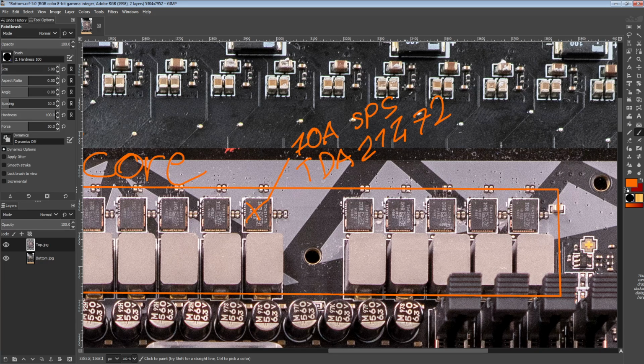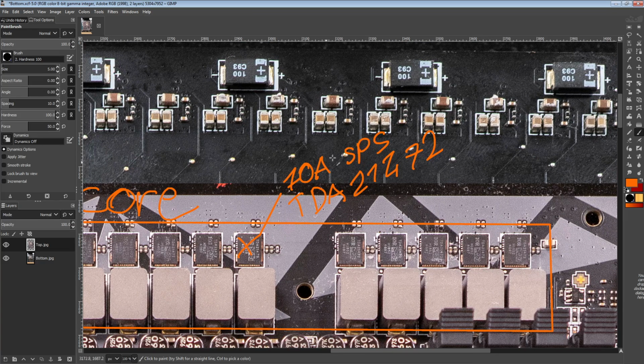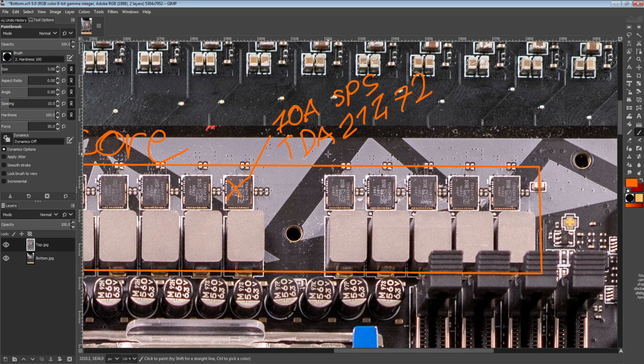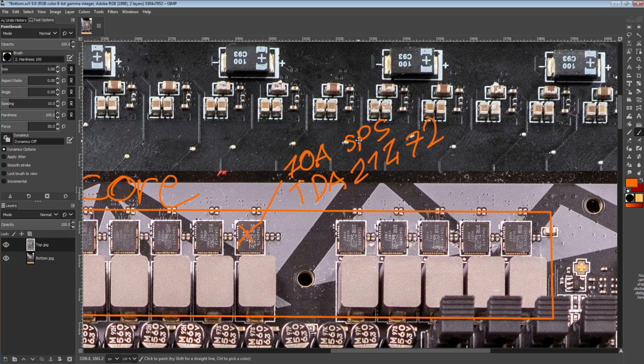So you get more power out at the same current output. So anyway, at 1.2 volts is not peak efficiency. You can get better efficiency at higher output voltages, but at 1.2 volts, a little bit under 94% efficiency is still really, really good.